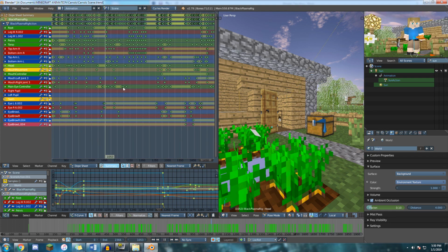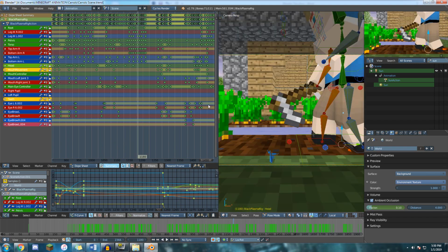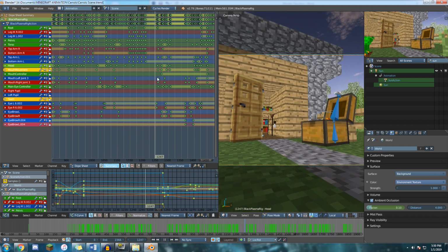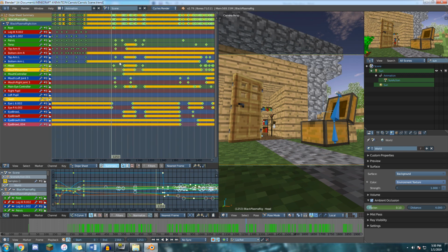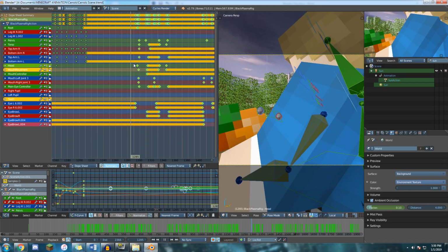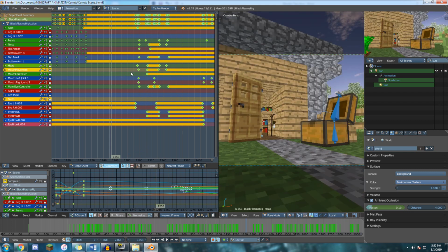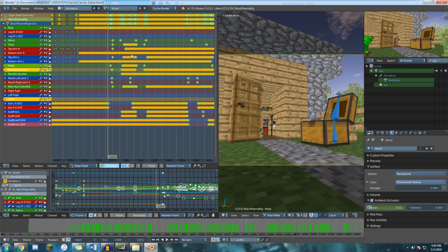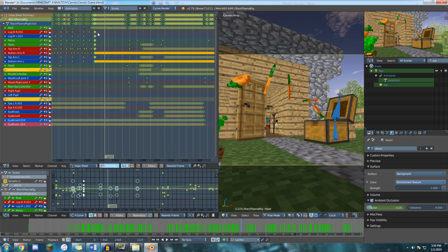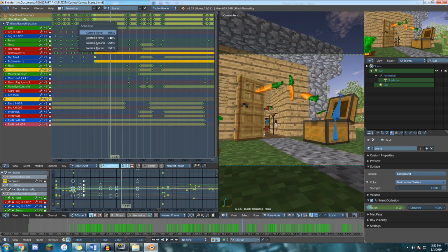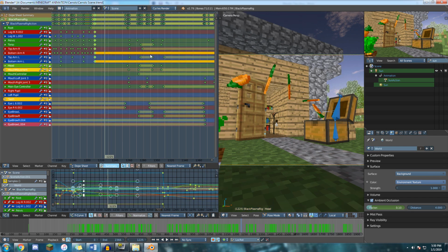And this is really useful if you're maybe right here and you want to extend the shot or something. You can just right click there and it'll grab all of them, move everything over, and it'll move everything beyond that point to the side, which is very useful. And just like with objects, we can grab a bunch of keyframes, go to a moment and do Shift S, and we can move keyframes to a frame just as we did other stuff in the viewport.